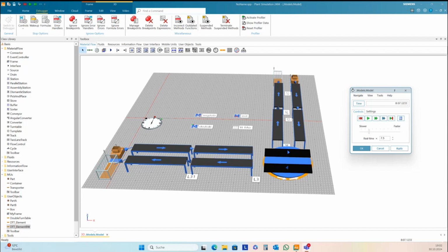Yes, but then you need to have exit controls in the conveyors to avoid the direct movement to the successors. And nevertheless, you need control for the turntable. But in Plant Simulation, for instance, if you have elements, you can use the attribute destination of the MU, and this you can use to select the right exit if you have more than one, and you can have 3 possible exits.